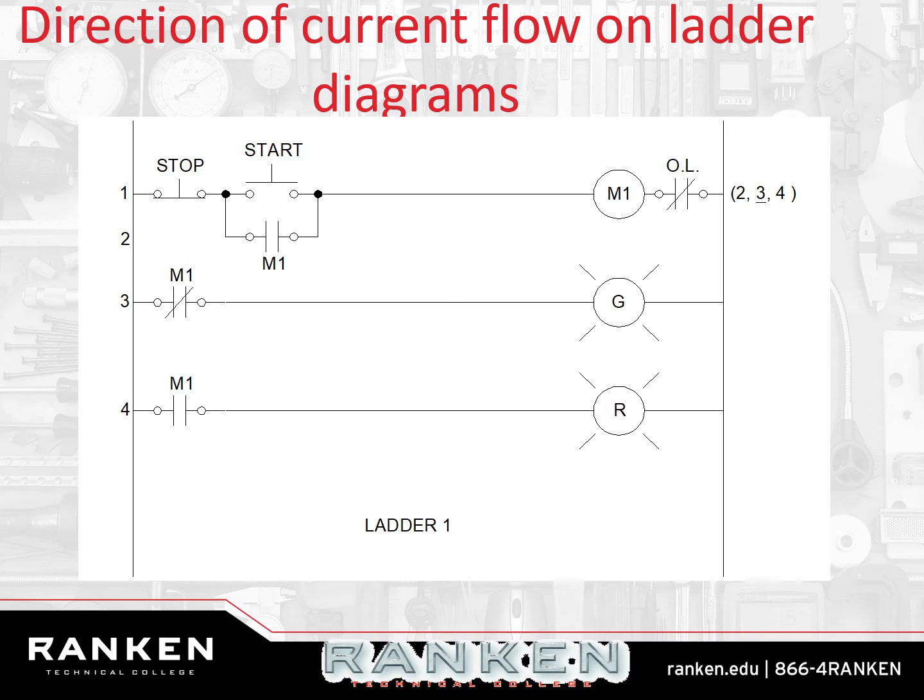So we're going to close that one because that's the pilot device, that's allowing me to actually interact with the circuit. I push it. Now Pooh Bear goes to the honey. Bang! Right? Now he has a signal, an action, and a decision. The decision was to turn on motor starter number 1, M1. Well, that causes a lot of other stuff to happen, right? A whole lot of other actions are going to take place. That's going to close, that's going to open, that's going to close. Now Pooh Bear's got more paths he's got to go. There's more jars of honey.